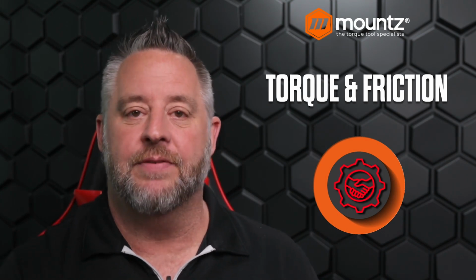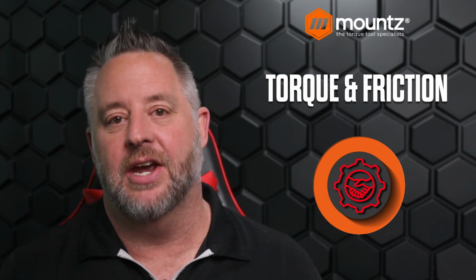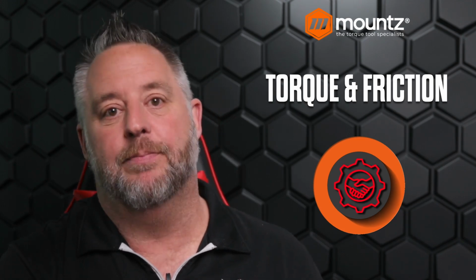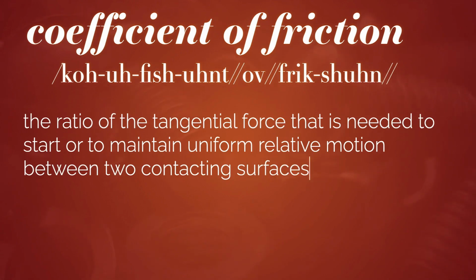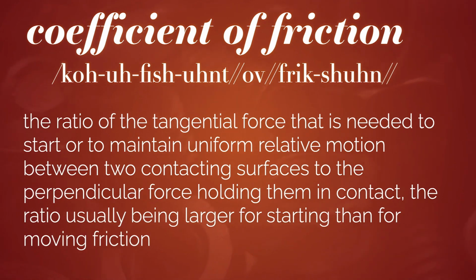So friction and torque kind of go hand in hand, and we typically look at friction as a coefficient of friction. And what that means by definition is the tangential force that is needed to start or maintain uniform relative motion between two contacting surfaces, with perpendicular forces holding them in contact. In most cases, it takes a little bit more force to get things moving. But once they are moving, then we have a constant coefficient of friction.